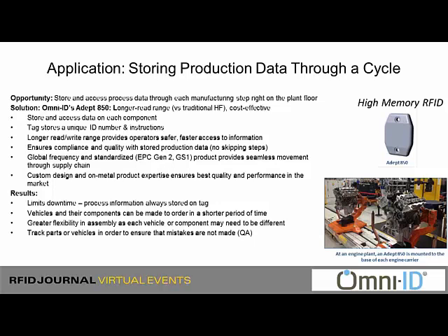But on the plant floor, for real-time control, there's a reliability factor that our automation engineers love about storing the information directly on the tag. This puts the PLC in control versus an upstairs network or an outside network, which they might not want to rely on the same way. We certainly also see the political divisions between plant floor IT and plant floor automation groups, and there's reasons why the automation group wants to keep control over this key production data and time stamping within the PLC cycles rather than up in the higher-end network.